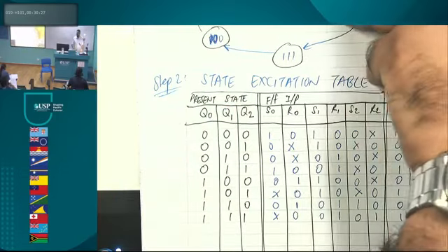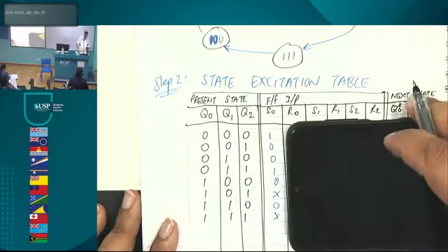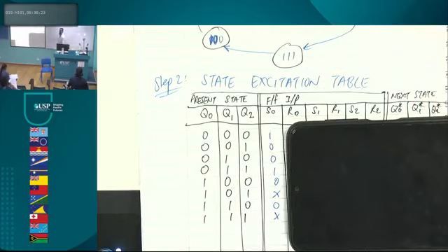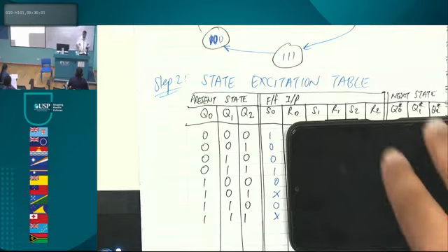Or, if you're smart, you know other ways you can make a function: sum of products, product of sums, Boolean algebra. You can even use a multiplexer or a decoder to get the function. You don't have to have an AND-OR function. You can do multiple things to drive that input into the AND gate.